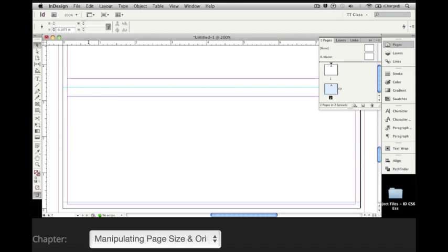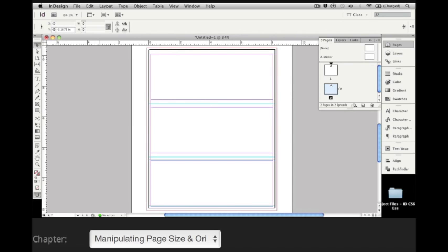So I'm going to go into my horizontal ruler. I'm going to set this in, as it's showing here at 3.125, and I'm going to bring that up to the point where it should be .1875. Now you'll notice once again I can't hit that number. That's okay. All I have to do is, with it highlighted, put exactly that number in from the control panel, and it'll adjust exactly the way I want it to be. I'm going to press Command 0 to go to my fit in window view.